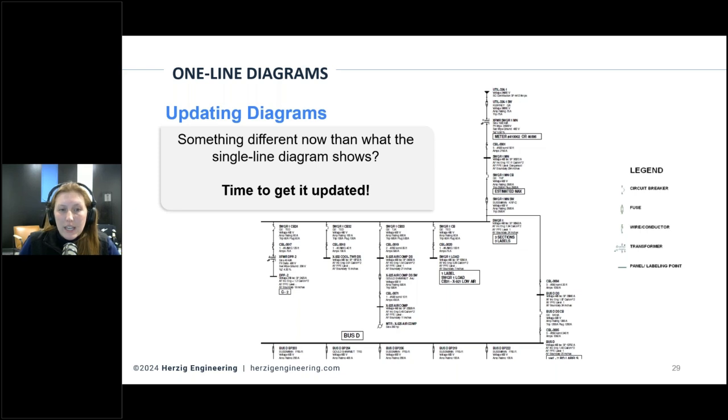And then there's this 60 amp rule mentioned, 60 amp breakers or 100 amp fuses, 50 horsepower. That is just based on our experience. So there's nothing necessarily that specifies those cutoffs, but based on our experience doing thousands of studies, there's a certain threshold after it's gone through a certain number of system protective devices. And if nothing's changed, there's no transformer, there's no large motors, there's no extra components that will then impact the results of the study further down to make it higher hazard. Yeah, typically we're not worried about updating those low hazard points.